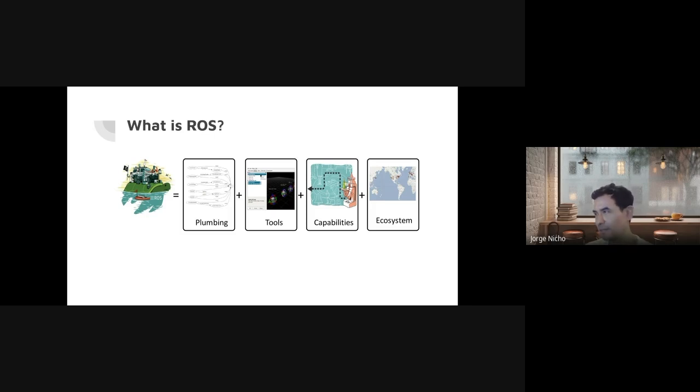There's capabilities. Capabilities refer to more higher level things. For instance, if you want to observe or detect an object, there's a perception capability that handles that, right? Or if you want to do motion planning, you have an arm and you want the robot end effector to go to a specific place, there's a whole process which involves generating a motion plan so the robot knows how to go from where it is to that goal position.